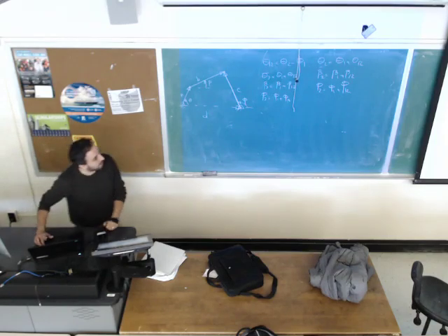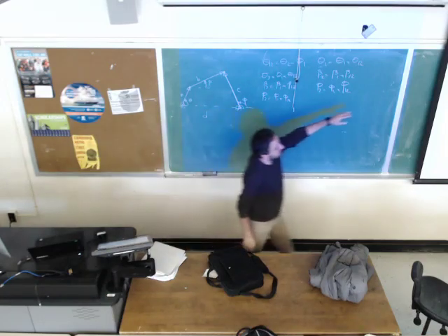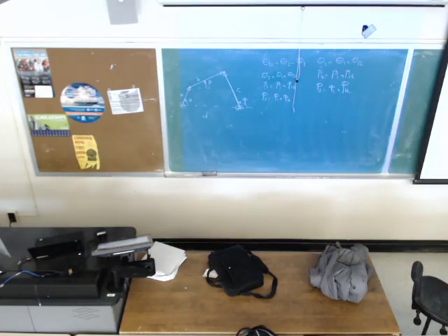So we end up with these 6 equations. The first 2 are for the first precision point, the second 2 are for the second precision point, and the third 2 are for the third. If I look at them, A, B, and C are unknowns. Theta 1 is unknown, beta 1 is unknown, and phi 1 is unknown. These are the angles of links 2, 3, and 4 at the first precision point.